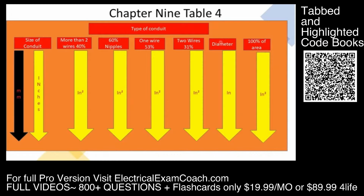of such and such conduit, this is where you find all your information for conduits, right here in the Chapter 9 Table 4 table. I will say this, I have had this final column on an exam before, the 100% area. It will ask you what the 100% area of a conduit is. All you have to do is remember to come to Chapter 9, Table 4, find your type of conduit, slide over here to the 100%, and you'll be able to look it up and find that one easy.